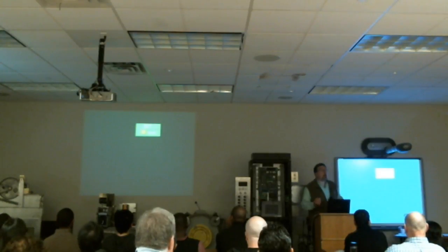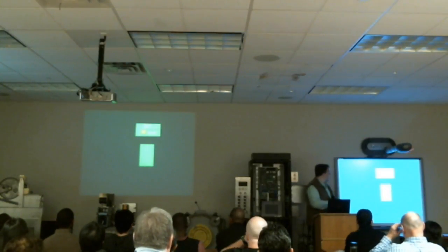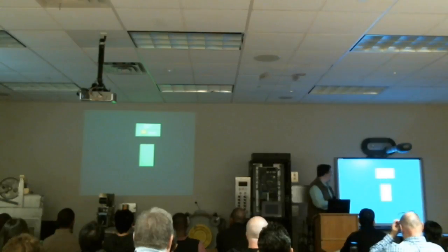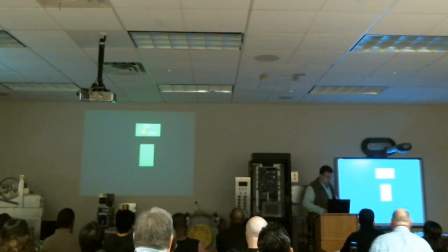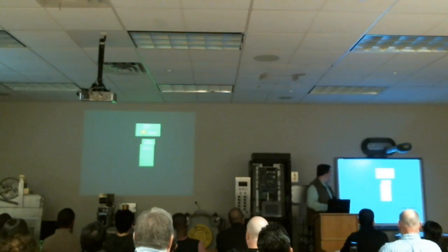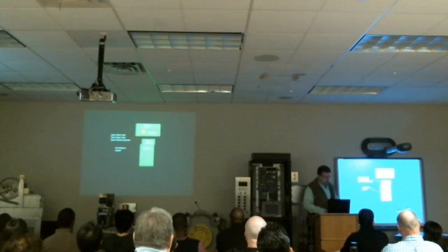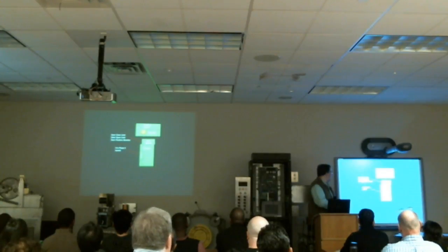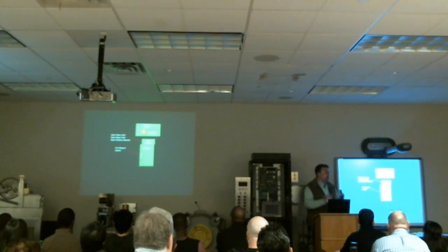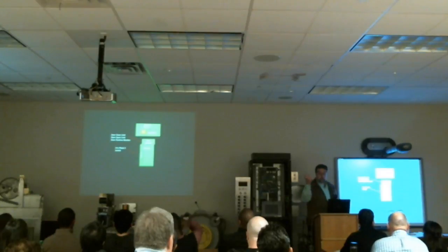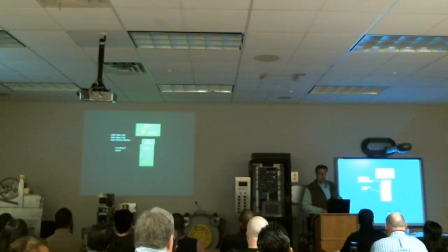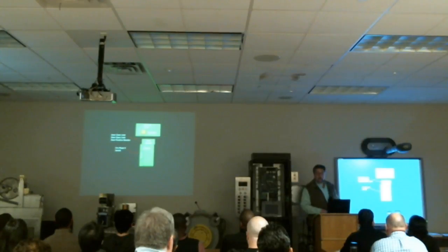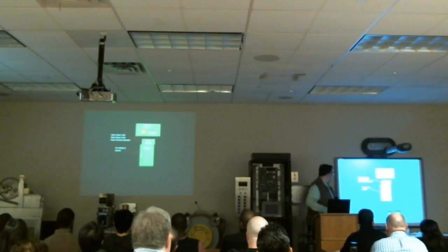Now, what do we need to do, pretty much? What is required to have? The door lock monitoring. Obviously, the door lock monitoring unit is going to be installed right next to the controller of the existing system here in the machine room. Then we have our elevator cab, where we have a door operator and a car operating panel. And what are some of the signals that we need? Well, we need to know the door closed and door open limits, because we need to know the status of the doors. That's number one. And also the door position monitor, DPM. Obviously on our MOVFR we have a DPM signal.